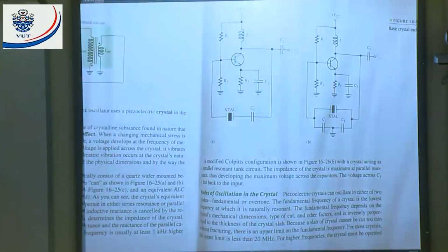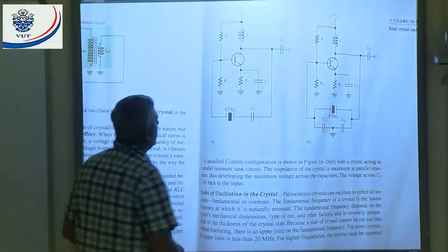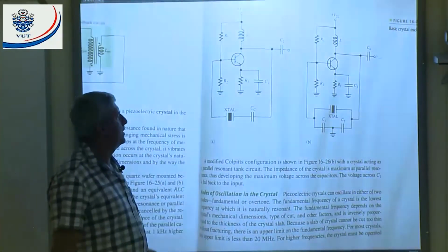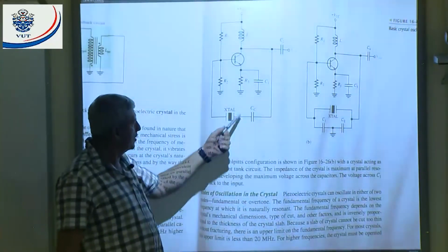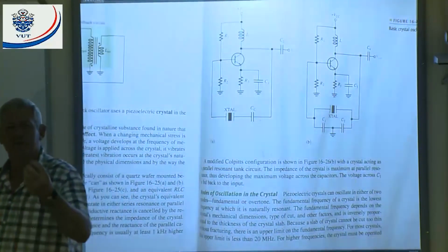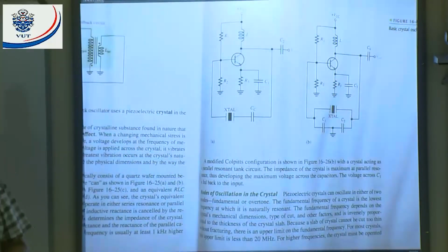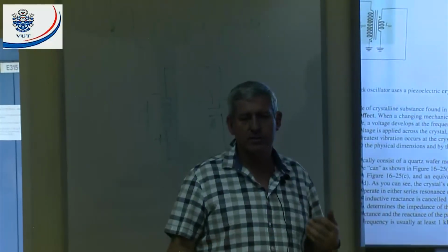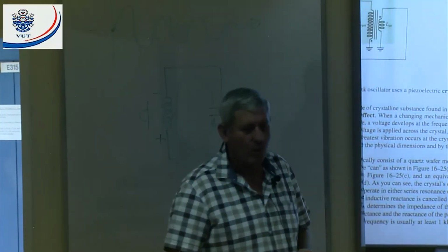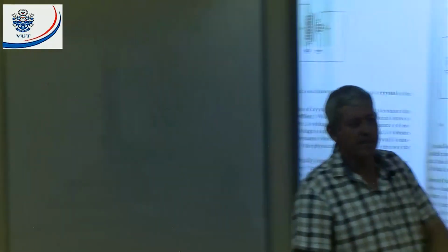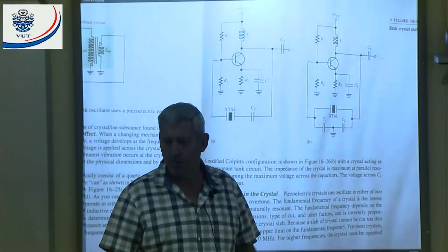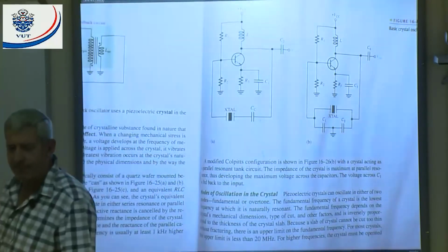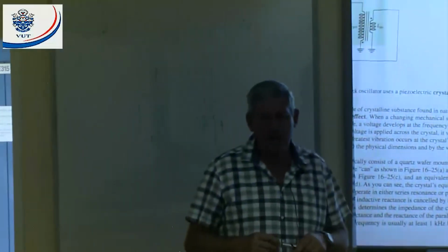All right, if you look at this, here are basically crystal oscillators. Again, an amplifier with the crystal in the feedback circuit. Talk about CC, the tuning capacitor. The first electronic watches you could buy. Most of the ones today have a liquid crystal display. Why a liquid crystal display? Because the power dissipation is very low, right? But the old watches had LED displays. That means they used much more power.